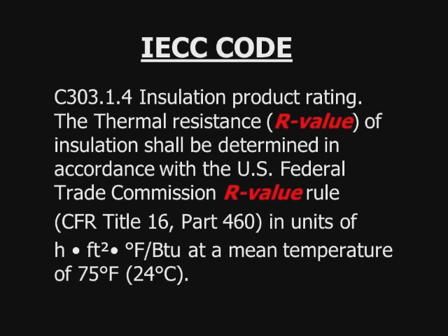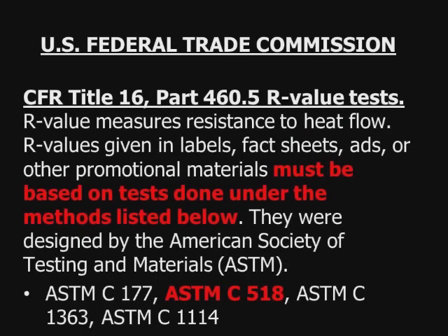If you take another look at IECC, you'll also see that they refer to the R value, that it should be determined in accordance with the U.S. Federal Trade Commission R value rule. Yes, there is an FTC R value rule, and it's in CFR Title 16, Part 460. The specific entry in the Code of Federal Regulations is Title 16, Part 460.5 for R value tests.